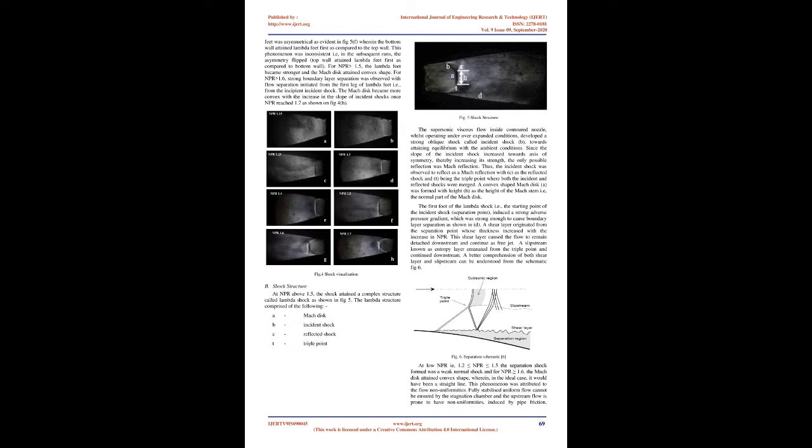The nozzle flow field was visualized by means of the Schlieren optical method, wherein the change in refractive index due to density variation is used to map the change in flow field. This method measures the first derivative of density, unlike shadowgraph, which measures the second derivative [7-9]. For the Schlieren visualization, a point light source, a monochromatic halogen lamp of 150 W, 2 concave mirrors of diameter 75 mm, gimbal mounts, adjustable apertures, a knife edge and a DSLR camera with a frame rate of 60 frames per second were used.